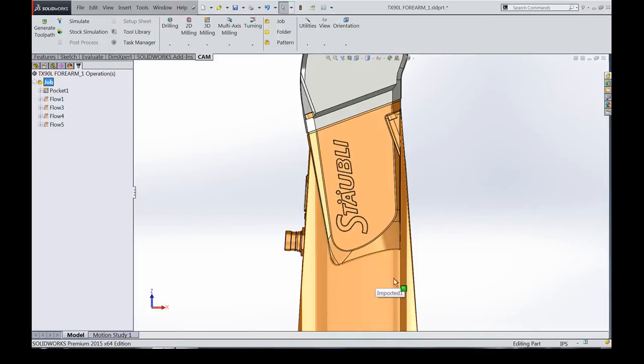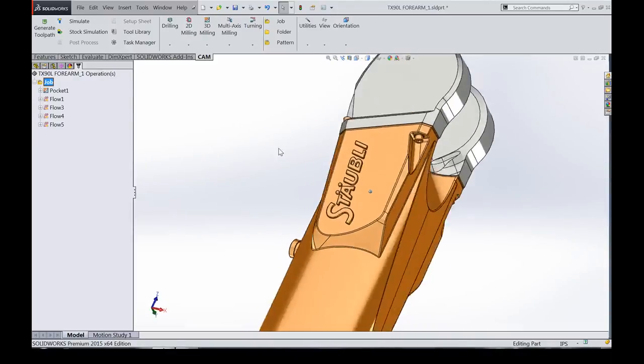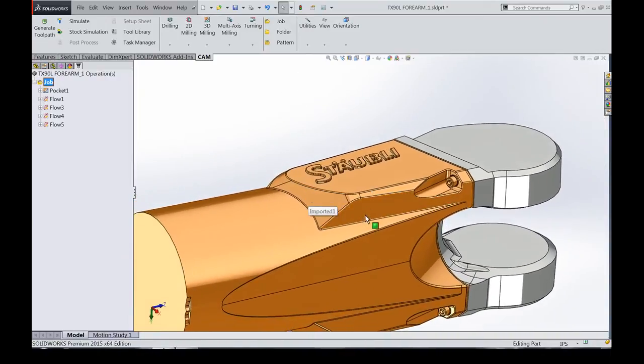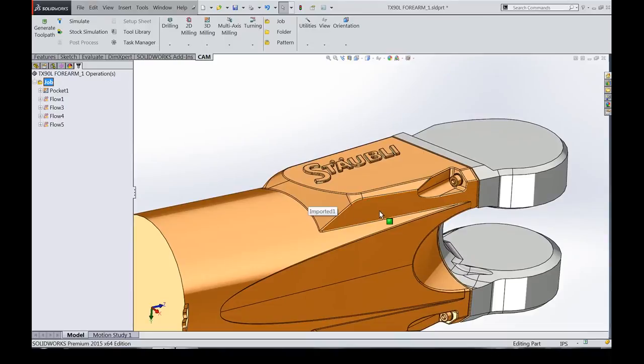It literally just fills in everything from one curve to the other curve in some set interval, and then projects that down. And so, much like parallel, because it's being projected down along the Z vector, when you get into areas that have a lot of steepness, it's not going to project along them very well. So use it mostly in places that are relatively shallow, not where there's a whole ton of contour.